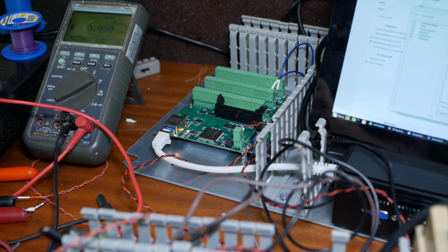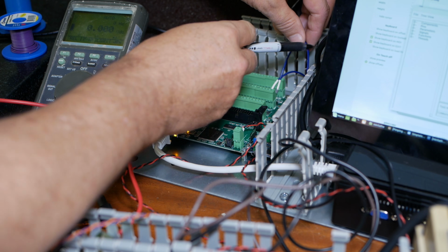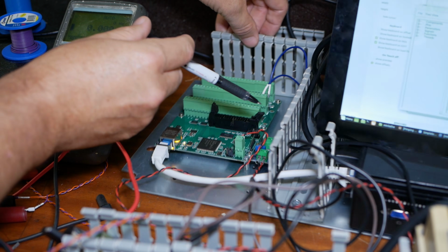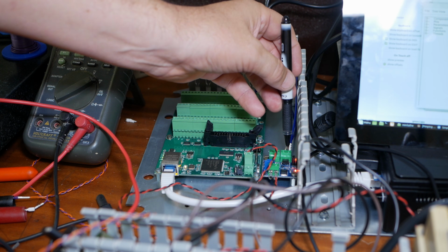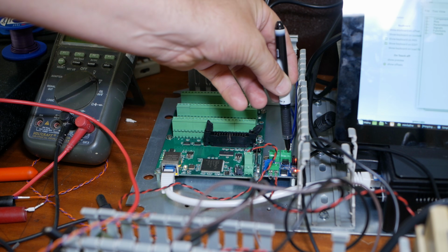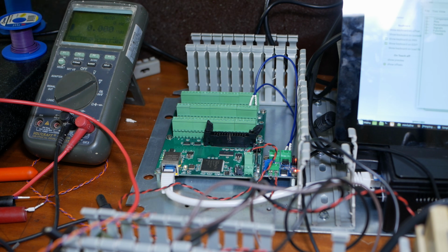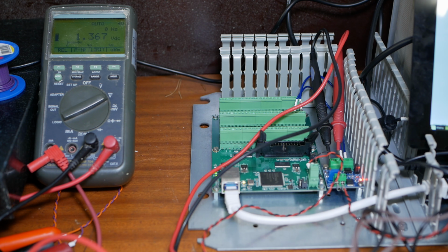Okay, now I see it. This is ground, and I've got it connected to this pin here, which is actually the positive pin. So I've got those two reversed. Yeah, I've set them full scale to be 2715 RPM. So if I set 2715, I should get 10 volt.